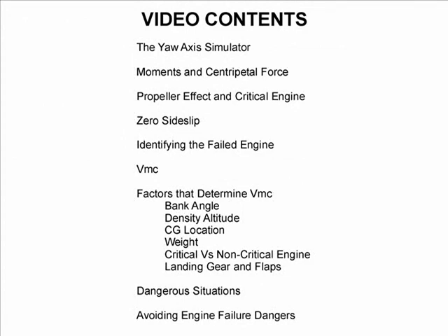In this video, we will look at a Yaw Axis Simulator, examine moments and centripetal force, define propeller effect and critical engine, cover the operational significance of zero sideslip, and ways of identifying a failed engine. Then we will explore VMC, including the factors that determine VMC.